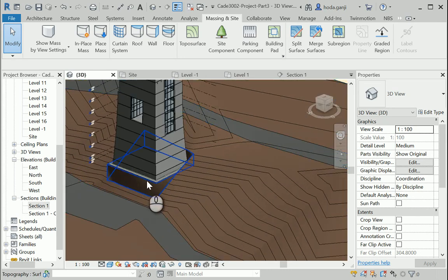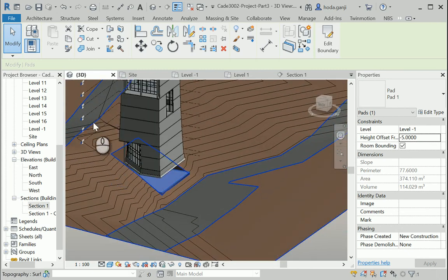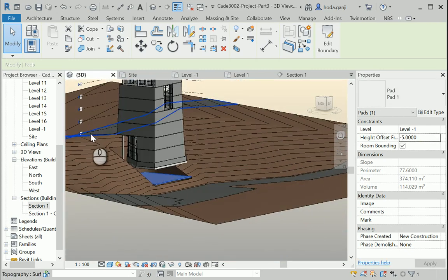So another way to go with it is to lower the building pad. So on one side, maybe even lower. You don't have to fill the soil below the path, but on the other side you're gonna have more cut. Or you might enter the building from like level 4 or 5 instead of level 2 or 3. So that also makes sense. It's up to you and your design.